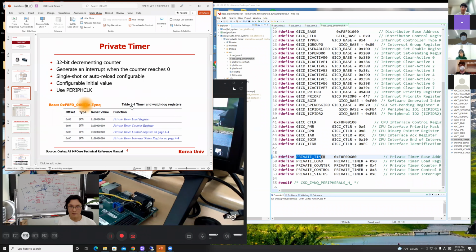I want to put 10 into the prescaler, so I did this: shift left 10 by 8 bits to position the 10 into that location. Then R1, I'm doing all operations with R1. I want to set bits 2, 1, 0: IRQ enable, interrupt enable, auto reload mode. 7 is 111, and the timer is enabled.